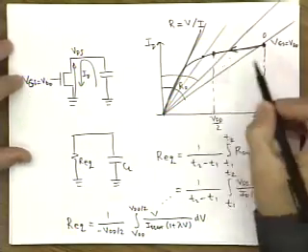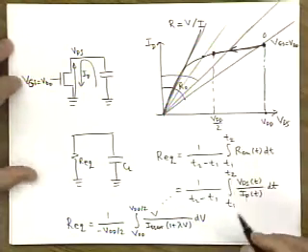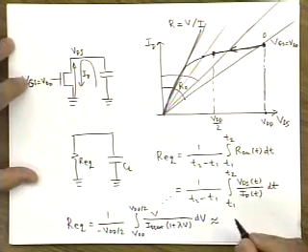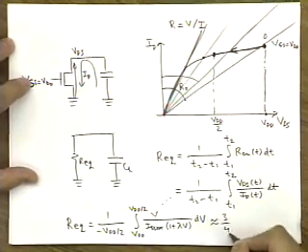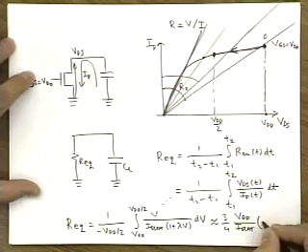But it is valid to assume that over here the transistor is in velocity saturation. When you solve this integral and do a little approximation, you have 3/4 VDD over ID sat times 1 minus 7/9 lambda times VDD.